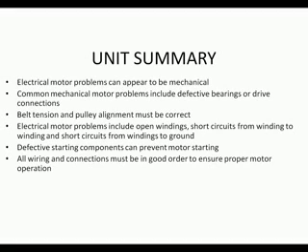Hermetic motors represent a special problem because they are sealed. They can only be checked electrically from outside the compressor shell. They experience the same problems as open-face motors: grounded circuits, open circuits, short circuits, and starting component problems.